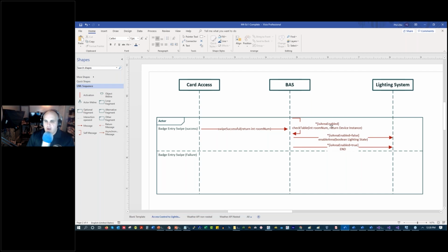So we're running a function, and I know this looks very programmatic. The reason I do this, and I know this is going to be uncomfortable to a lot of building automation folks because we don't think this way, is that if you want to start working on complex integrations to non-building systems like flight traffic management systems or nurse call systems or telemetry systems, then you're going to be dealing with APIs and data types, programmatic data types.